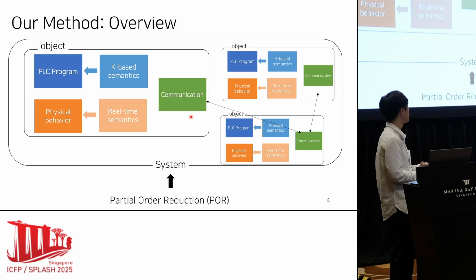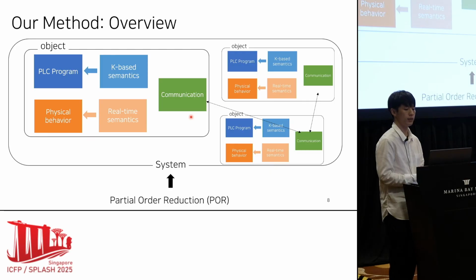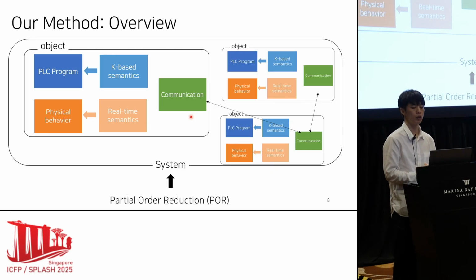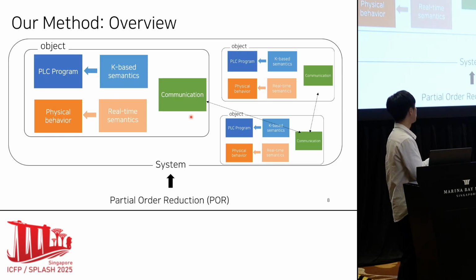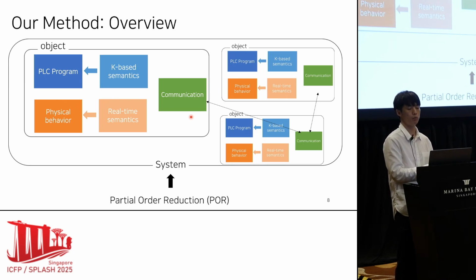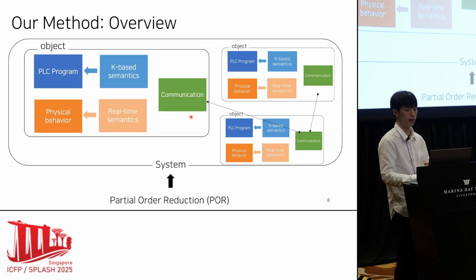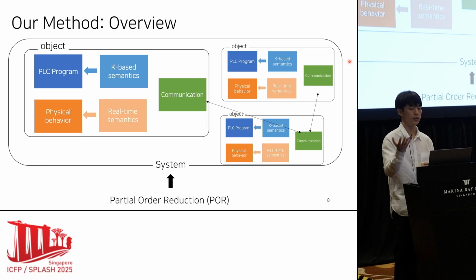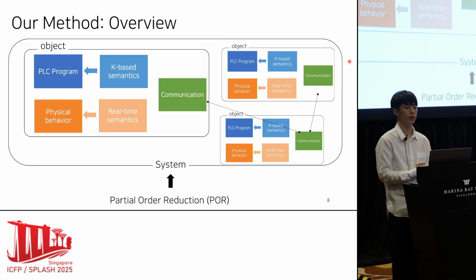In short, we take an object-oriented approach for modeling PLC systems. The PLC programming language semantics is covered by our K-based semantics, and the physical behavior is covered by the rewrite-based real-time semantics, and I'll talk about it in more detail in a minute. The system will be a set of PLC objects like these communicating with each other. The system is basically the set of these objects, and we want to apply partial order reduction, in short POR, on the whole system to deal with the high complexity.